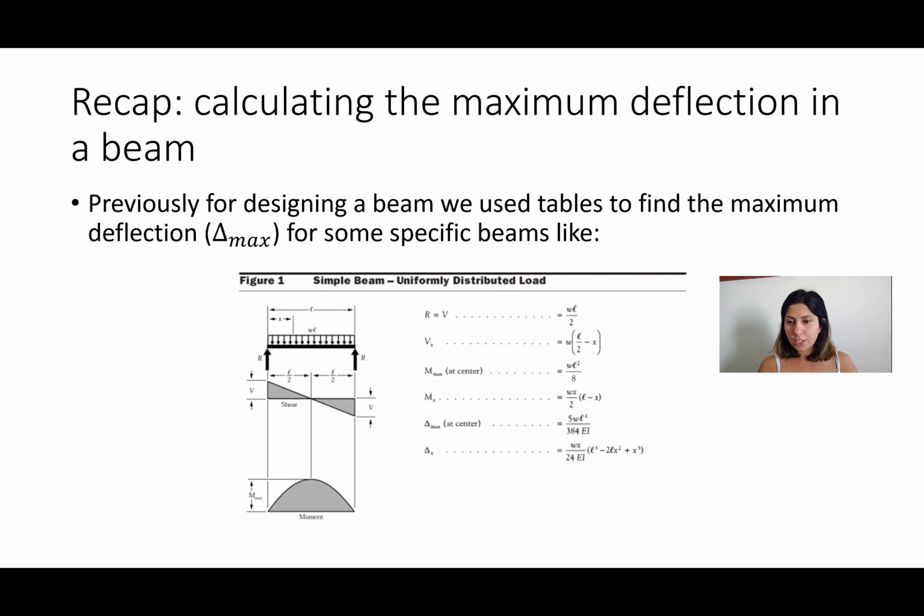When we say deflection, we mean sagging. So if it is a straight beam and you apply a load on it, it will deform. This displacement, we call it deflection of the beam. And when it happens, as you can see, there is also a rotation. So we want to see how we can calculate this rotation as well as the maximum deflection or the deflection at any point in the beam.